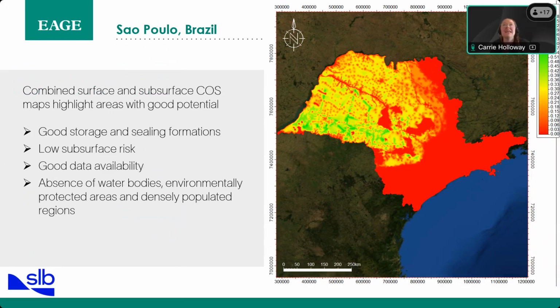Okay, so here we were looking at the onshore basin. The critical point was actually where we had formations at depth to store the CO2. The basin extends to around, well, just outside this red line here, because outside of this, we don't have a thick enough section of the basin to actually get that CO2 to the supercritical depths, which is at around 800 meters.